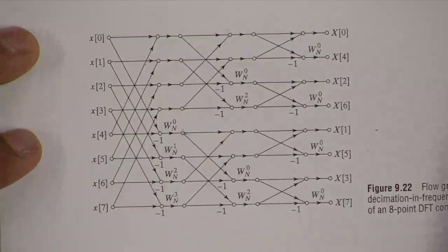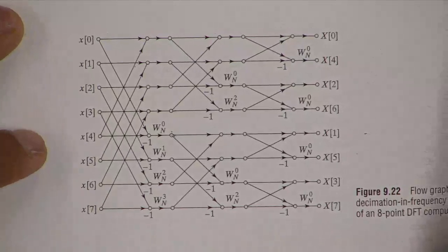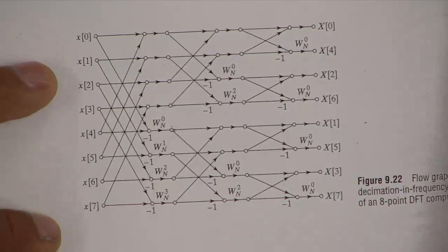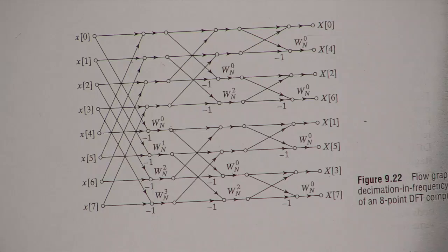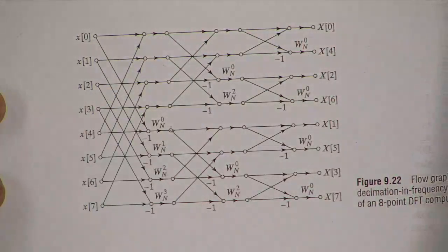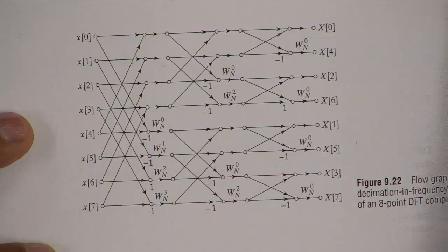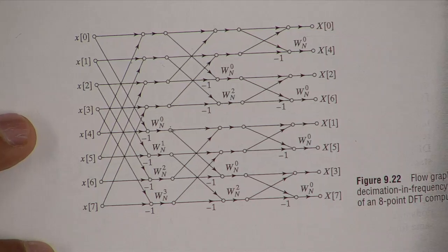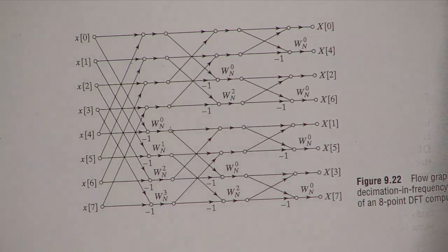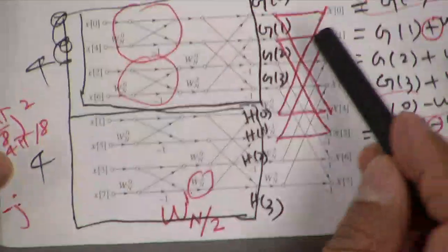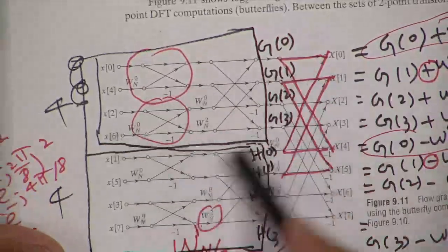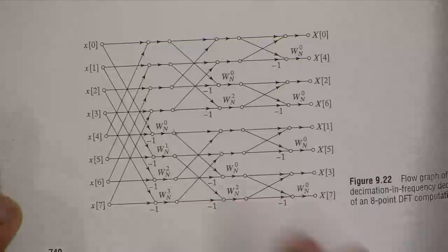Okay, so we have spent a lot of time talking about the Cooley-Tukey decimation in time and decimation in frequency algorithms, but many of these are really equivalent. There wasn't really a need to derive this from decomposing the odd and even; we could get to that very quickly by simply transposing. If you take the 8-point decimation in time, just transpose that, so just reverse the directions of the edges, and then you will get back the decimation in frequency.